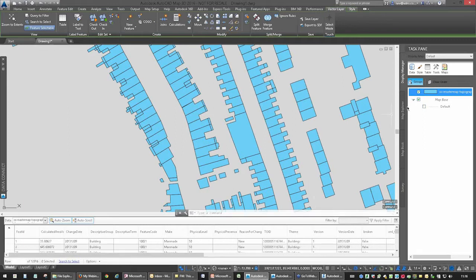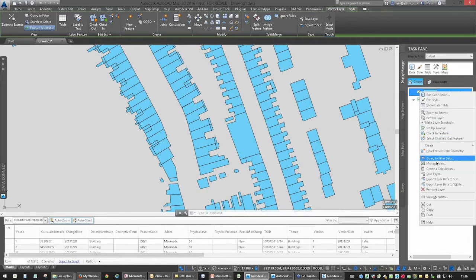Remembering those buildings have got the height data. So now, the quickest way is to right click it and export the layer to an SDF file. You can do it to an SQLite file now, and interestingly SQLite is what InfoWorks works on, so that's a really good way of doing it. If you want to export to sources that are not Autodesk-y, then SDF isn't useful, whereas SQLite is more useful.